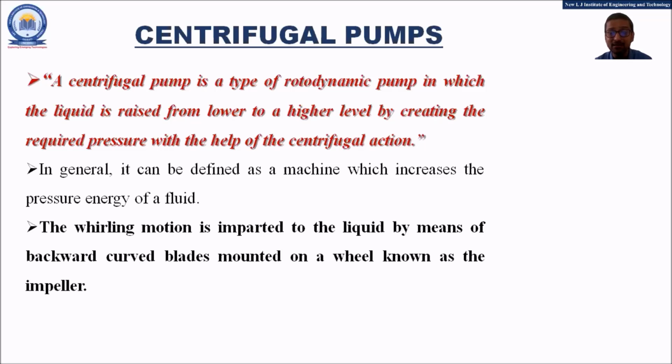Dear friends, the impeller is one of the most important components of the centrifugal pump. You can correlate the impeller with the fan which we use at our homes. But in the fan, we observe the blades are straight in design. When we consider the design of the impeller, it has backward curved blades. So this is a very important concept in the context of centrifugal pumps.